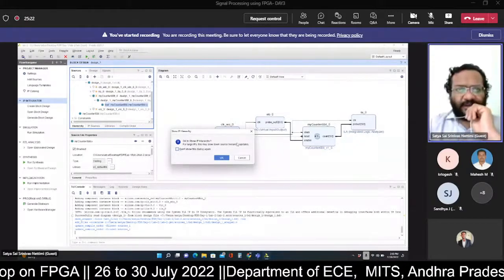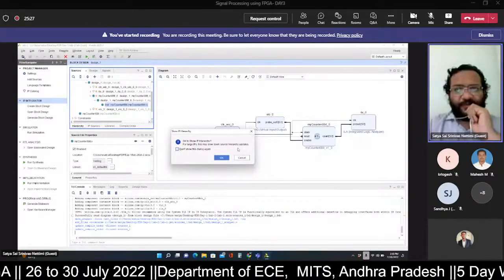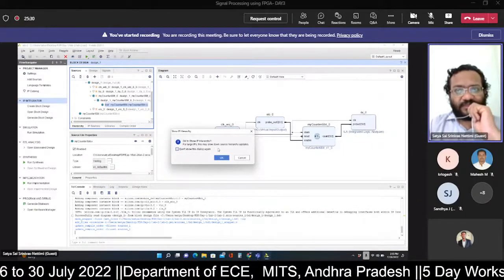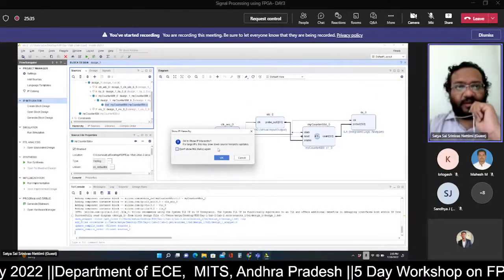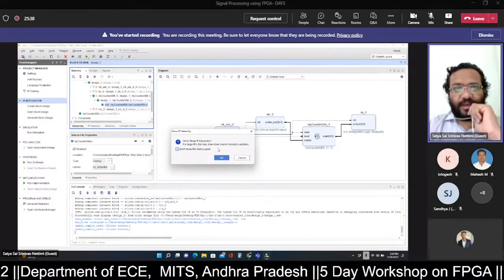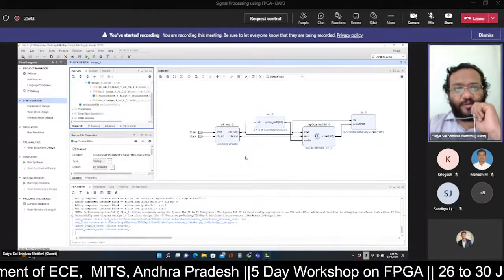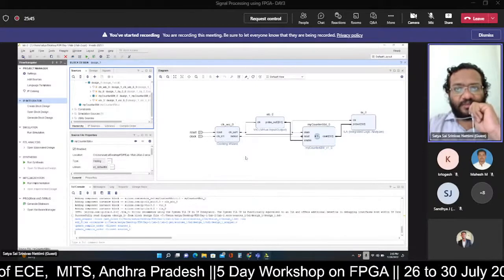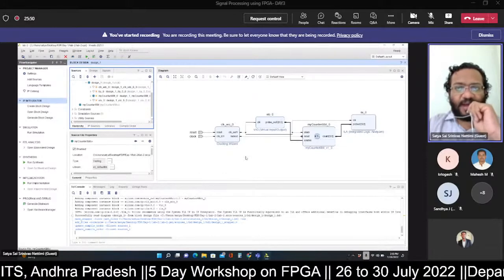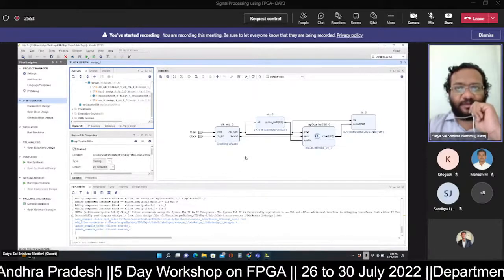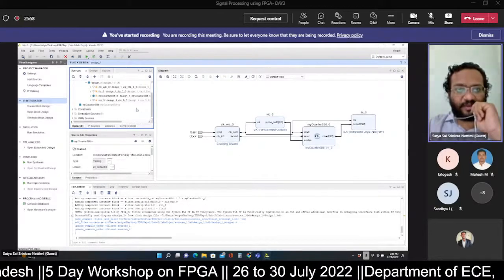For inbuilt IPs, depending upon the type of license you have, you can only go to a certain hierarchical level. You cannot see all the files associated with that IP, because those files will be encrypted from the Xilinx side. So you only have plug-and-play control: just drop it in your design environment, make connections and use it. You'll have the reference manuals on how to customize the IP and how to use it in your designs. That is the only thing accessible.